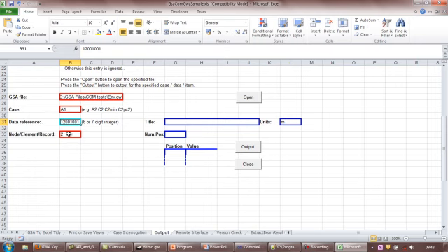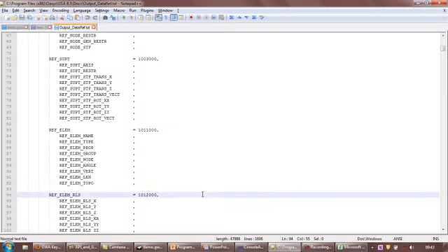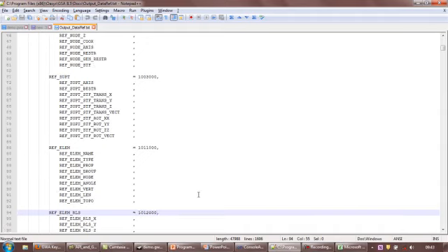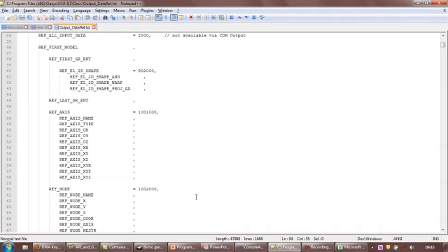So if we want the Y translation for the node, we need to supply an integer that corresponds to the Y translation, and that's where the output_data_ref file comes in handy, because it documents all the enumerated values for the result types that GSA has available.